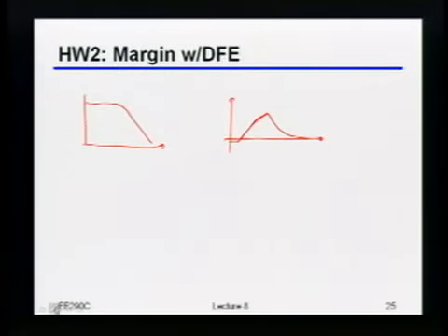Most everyone figured out that one thing interesting about this type of channel was that, because there's a very well-defined relationship between each and every value of the residual ISI, all it took to cancel all of the later taps was to arrange it so that at just one point, you had either a DFE or, in this case, the FIR that put in exactly enough energy to cancel that one thing.